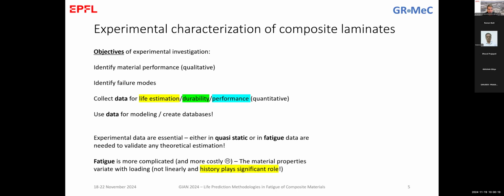So what we've seen there is that when we were doing interruptions of the testing for several reasons, either for maintaining the testing rig or for doing a modal testing on the blade, when we were reinitiating the blade test, we were observing very, very good properties, or much better stiffness, fatigue stiffness for the material. And this triggered this curiosity to see what happens. And this is exactly what we've seen, that there is a significant effect of this interruption.